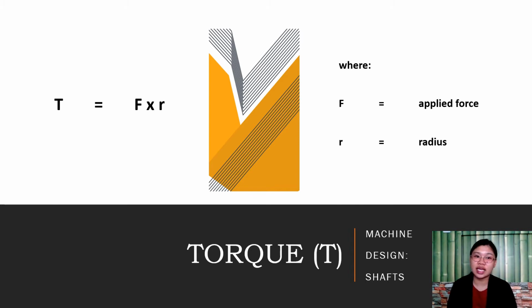So you still need to convert pound force inch to pound force feet before applying it to P equals 2 pi T N over 33,000 to arrive at the HP power. To arrive at a unit which is horsepower, or to use the English formula for the power, you must always be mindful of the units that you are using, since I mentioned earlier that it is an empirical formula. So let's proceed to the next.